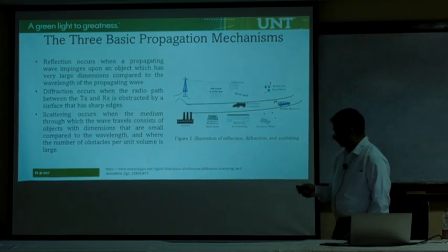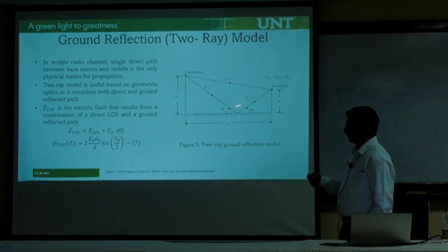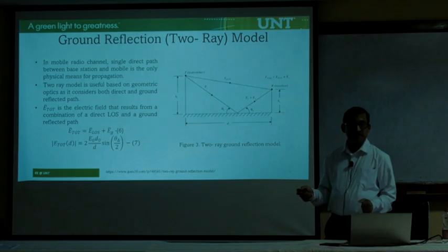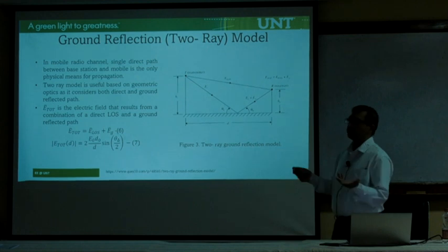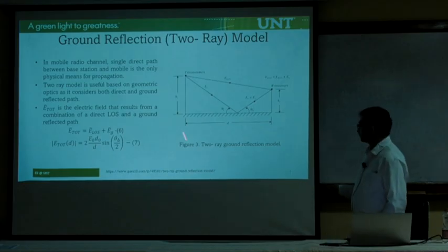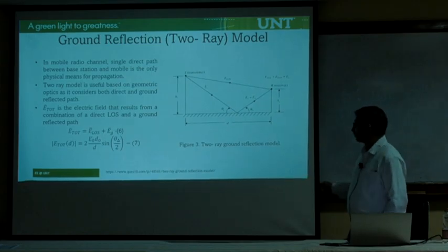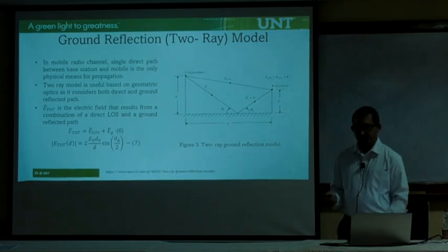Okay. But here, I'm just showing you one path, one non-line of sight in addition to one line of sight. Practically, we need to consider more non-line of sight paths. And then we'll get into that. What do you get out of it? We will learn. In the book, actually, this problem is explained very well. The geometry is explained very well by using something called reflection. If you reflect this whole thing on the bottom, then using that geometry, you can compute all these path distances much more efficiently. So take a look at Rappaport's book, please.